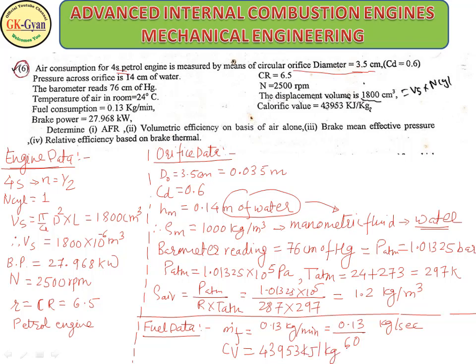So this is the data of this engine. We have to determine air fuel ratio AFR, then volumetric efficiency based on air alone, then brake mean effective pressure, and fourth, relative efficiency based on the brake thermal. So first we have to calculate air fuel ratio.